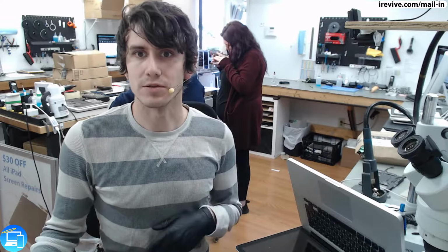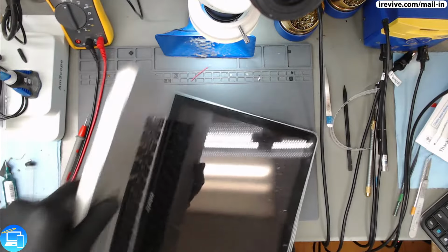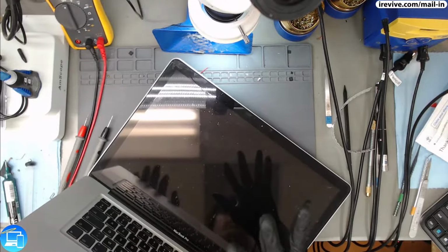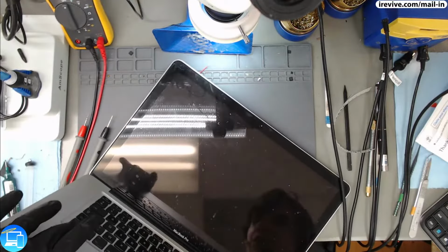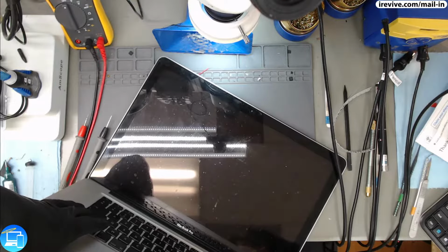So first thing I'm going to do is go ahead and show you. I have a 2011 15-inch MacBook Pro here that does have a failed graphics card. And how we can check that out is if we have any weird lines, discoloration. I'm going to try booting this one into safe mode. And this one has some very obvious blue lines in the screen.